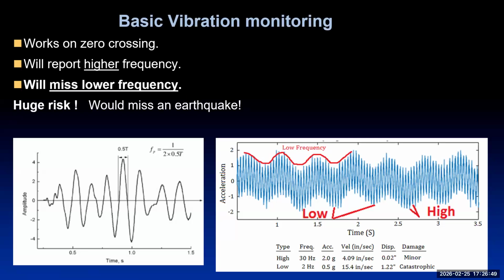The problem is this: they only report the lowest or the highest frequency because that is in the time history. So they're completely ignoring all of the other low frequency components here. So it inherently is misrepresenting the data by only measuring one frequency, and it's only measuring the one that has the smallest amount of displacement. It could be the dominant frequency, or it may not be the dominant frequency.